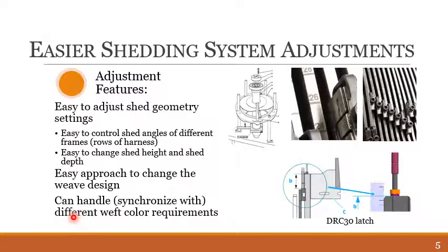Another approach that can be provided by a manufacturer is the synchronization of the different weft insertion channels. For example, if you are using four colors and there is a break in the machine, a weft break, the machine must be capable to find out which yarn was broken and which yarn is to be inserted, especially when you are going forward and backward in pick finding. This synchronization must be available there. A good shading system, or maybe a good machine, must incorporate such type of settings so that there must not be a complexity or fault in the design.